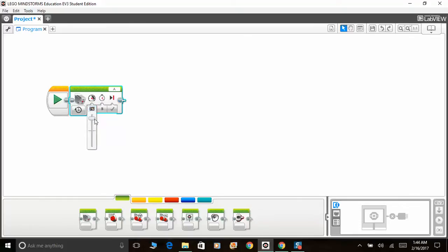However, we are allowed to set a negative parameter, for example negative 60, negative 80, and negative 100. For the specific medium motor, if we set the motor at a positive rate, it means that the motor will move in the clockwise motion, while if you set it to negative, it will move the other direction, anti-clockwise.